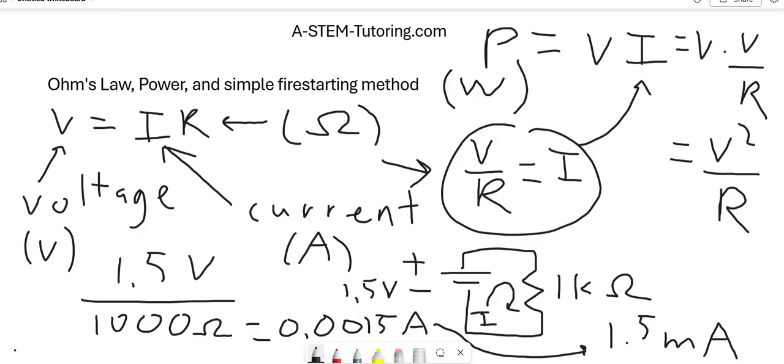And again, if we lowered the resistance, the amount of current flowing would increase, as would the power dissipation. So if you have a fixed voltage source, which most batteries are, for example, a AA battery, your car battery is 12 volts, a 9-volt battery obviously supplies 9 volts, things like that. If you have a fixed voltage source, then a lower resistance in the circuit gives you more current flow and also more power flowing through the circuit.